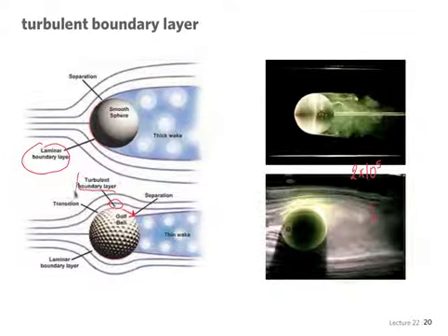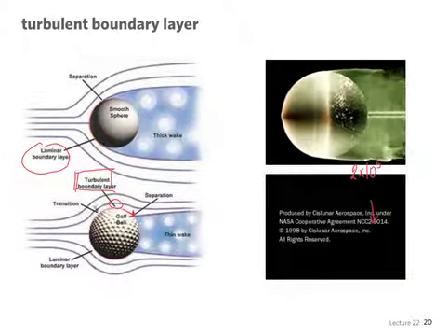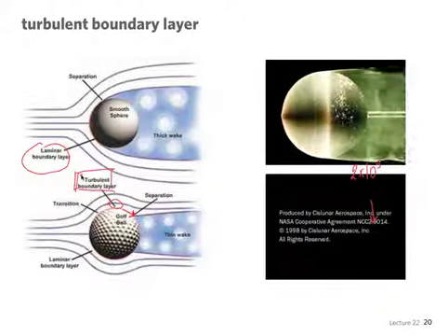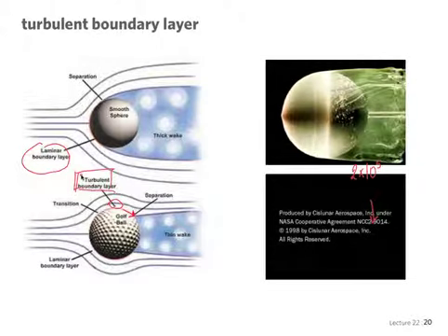Then instead of the separation, what you have is some sort of transition here at the front. There's always boundary layers, transitions from laminar to turbulent. When it becomes turbulent, it's just the increase of momentum flux that the turbulent boundary layer has, allows it to go around the curved path easier so that it delays the point of separation further down the back.